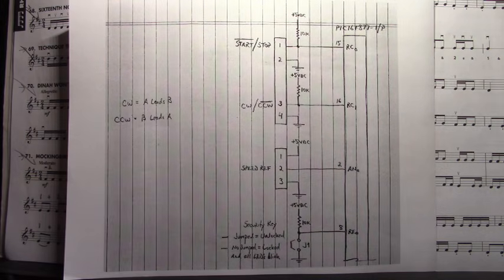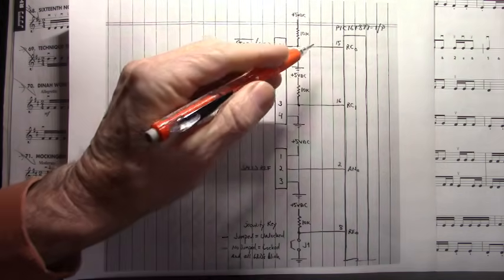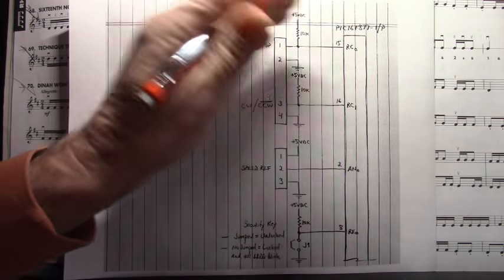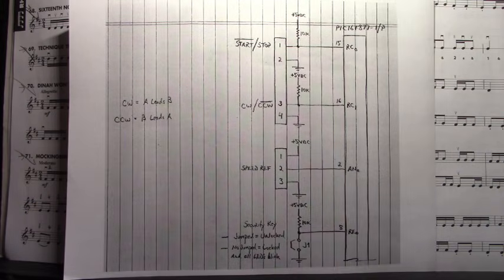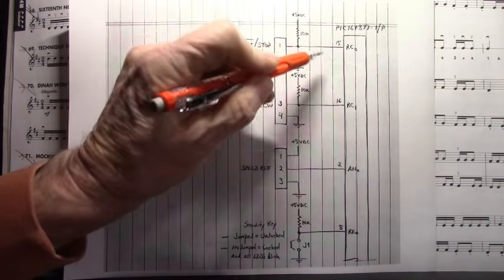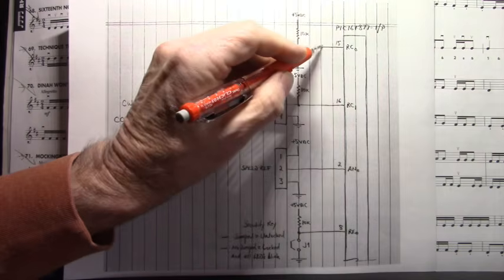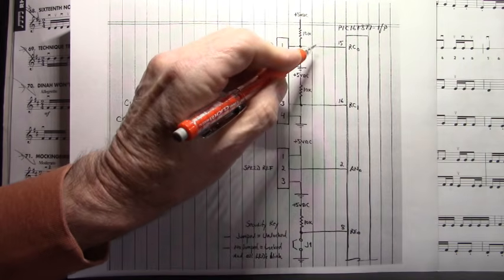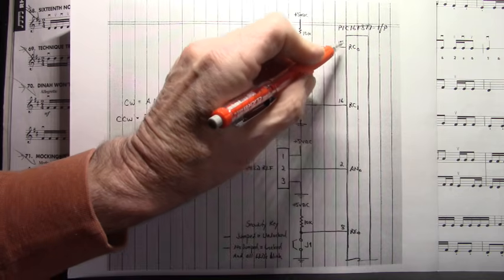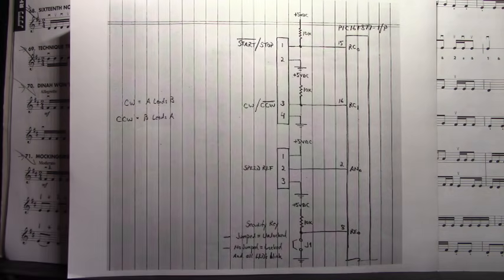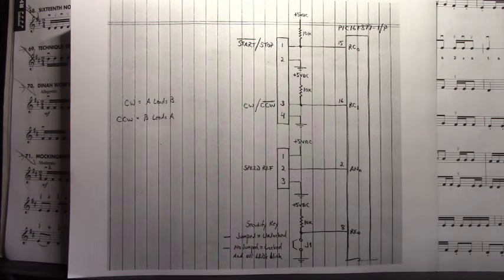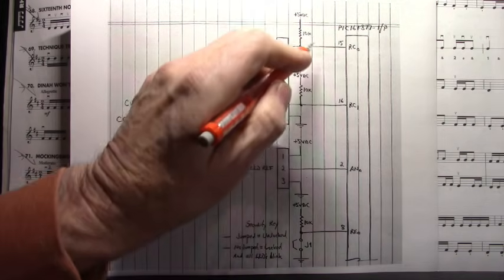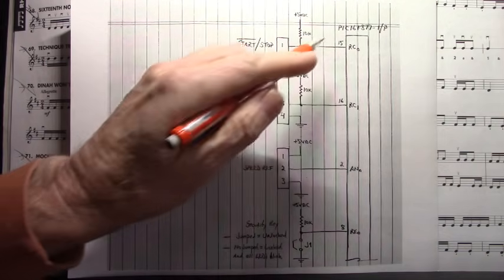If you had an optocoupler, it would be opposite. So the output of the optocoupler, when 5 volts is applied to the anode and cathode, or I'm sorry, to the anode, that optocoupler would be turned on, so you'd have 5 volts on the input, but 0 volts on the output, because that photo transistor would be turned on, pulling pin 15 to ground. Whew! Okay, so remember, if you do add an optocoupler, you're going to have some inversion.